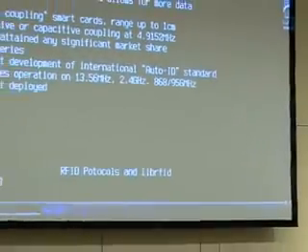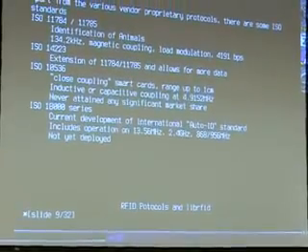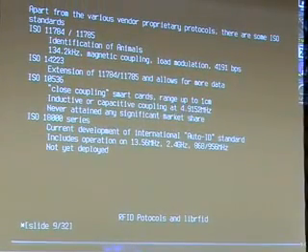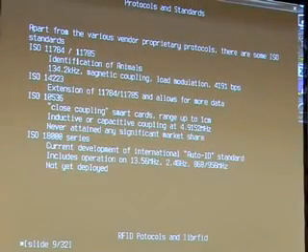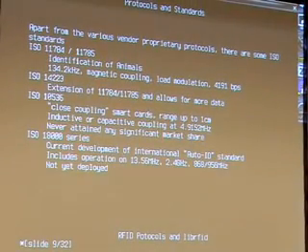A couple of standards, real standards as in openly documented international standards that we have in the RFID area, are listed here. There's ISO 11784-785, which is used for identification of animals. So for example, here in Berlin, if you register a dog, then that dog has to have an RFID transponder implanted in case the dog is found somewhere, so that the owner can be located. That's what is being used here. It's very low bandwidth, 4,000 BPS, but well, how much do you need? It's just some unique number to identify the owner of the dog. There's an extension which allows you to put more data into that. It's called ISO 14223.